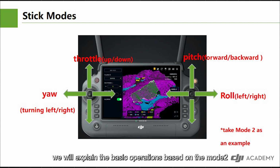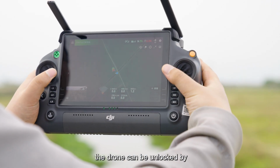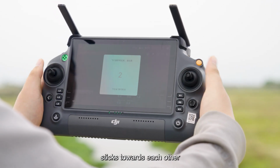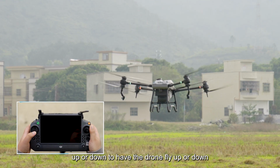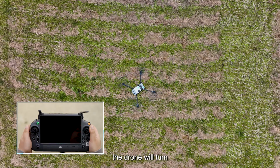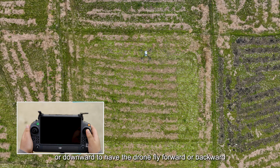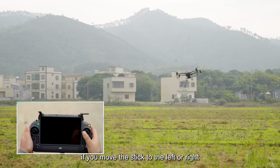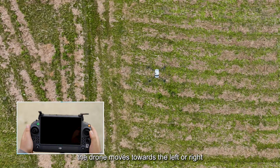We will explain the basic operations based on the mode too. The drone can be unlocked by simultaneously moving the 2 sticks towards each other. Move the stick on the left, up or down to have the drone fly up or down. If you move the stick to the left or right, the drone will turn left or right. Move the stick on the right upward or downward to have the drone fly forward or backward. If you move the stick to the left or right, the drone moves towards the left or right.